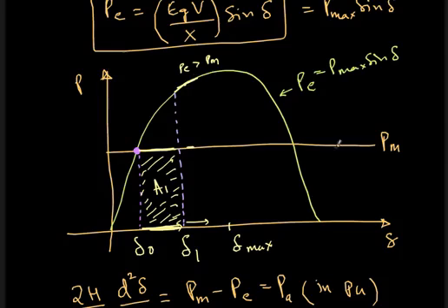During the duration of the fault, we are assuming mechanical power is always constant, because in that short few milliseconds, not much variation will be there in the mechanical input to the machine. So, since PE is more than PM, the accelerating power is negative. That means the rotor is actually decelerating. Therefore, it cannot go on forever. There will be some maximum point it will reach, and then after reaching that maximum point, the machine will come back to its original point here after a few oscillations, assuming that the oscillations are going to be damped because of some friction or some losses and so on.